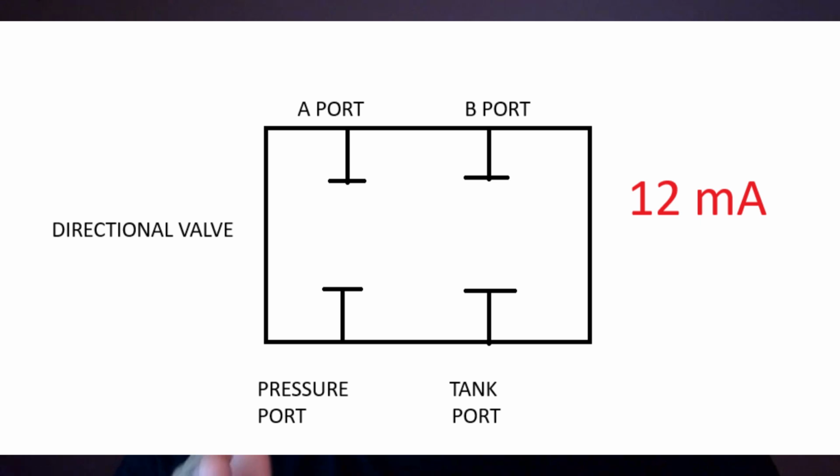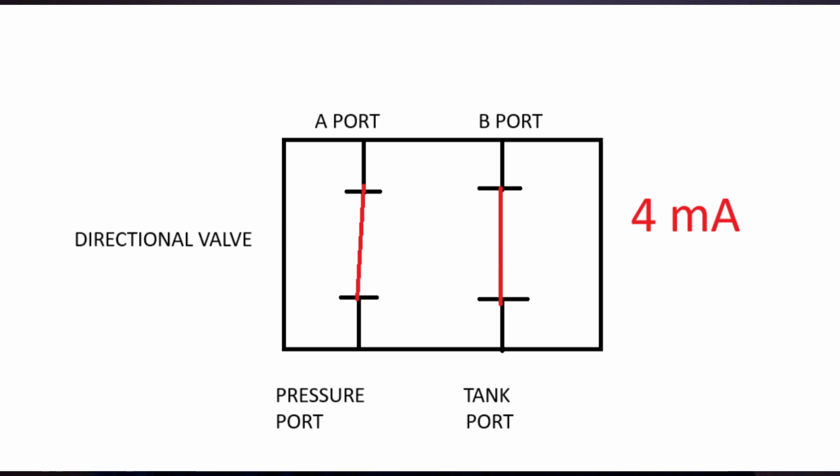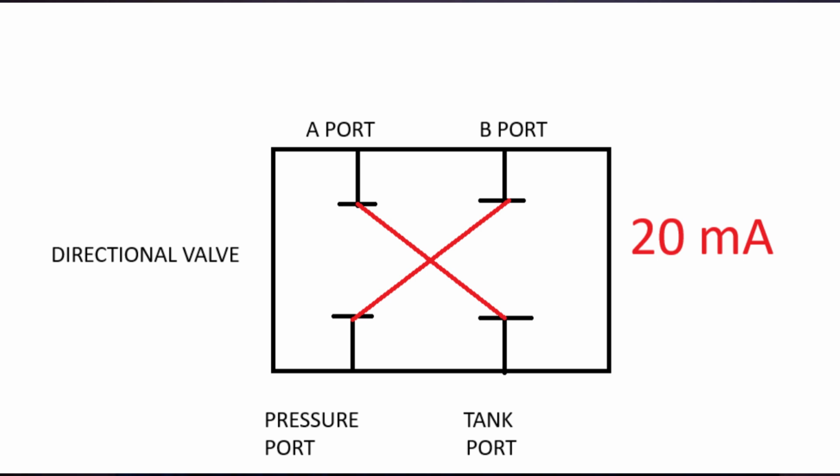Another quick thing I want to hit on is we've been talking about what happens with a 4 to 20 on an input device, or anything inputting information to a PLC. Well, the PLC can also output a 4 to 20 milliamp signal to something like a proportional valve that controls hydraulics. This situation is a little bit different because a proportional valve has an A and a B side, say for a direction, and the very middle is closed, so no movement. So then 12 milliamps is going to be closed, and 4 milliamps is A side all the way open, and 20 milliamps is B side all the way open.